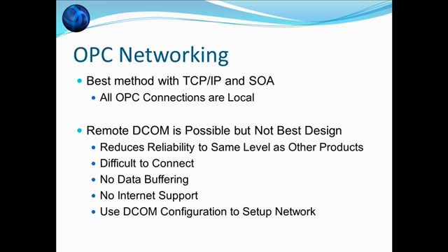And at the end of this presentation, we're going to review the best practice to implement OPC networking. The easiest way is to use the features that we'll demonstrate in the first part of the video. OPC Systems.Net also supports remote DCOM, but we'll see that by implementing remote DCOM you lose a level of reliability in that if your network goes down, you have lost the data. Also, by implementing remote OPC, we'll see that it's difficult to set up and difficult to connect to remote OPC servers unless you have the remote connectivity.